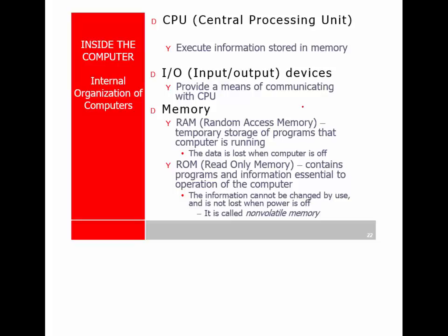The old type of ROM, when you built the chip, the code was in the chip. You bought a 2016 chip from Intel. You had to tell them what you want to put in the 2016. You could buy a 2716, and the 7 means that's erasable.